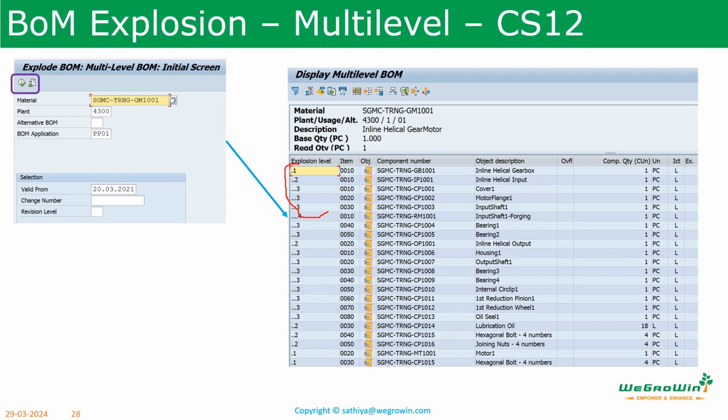So to understand this, the level of the BOM, the 1, 2, 3 that we mentioned, we have to understand what the level is. When you see this level, reading the bill of material will be easy. Level by level BOM is used for some purposes, and multi-level BOM is used for other purposes. For example, if we want to find out the root cause of a wrong bill of material quantity, we can use this multi-level BOM. We can take one branch and see until the end of this BOM what is happening, how the materials are carried over from one level to another level.